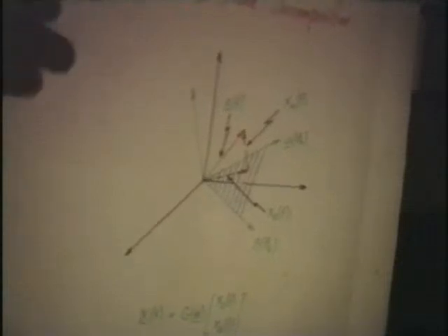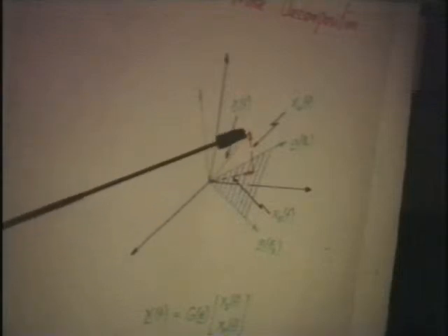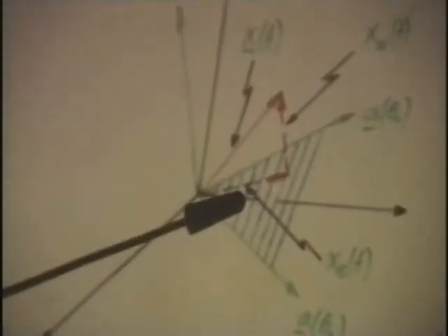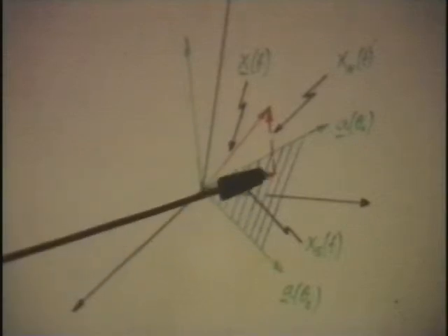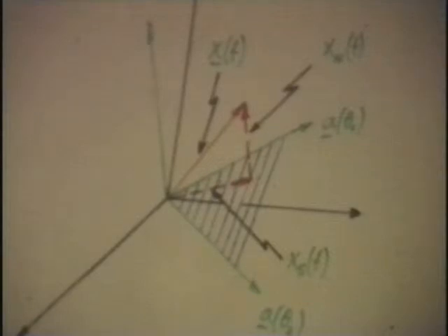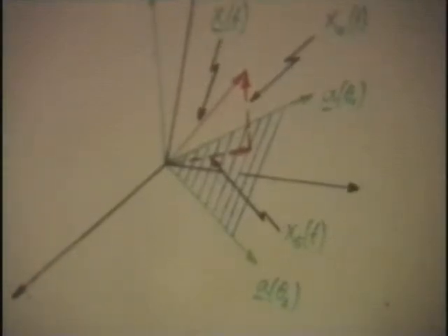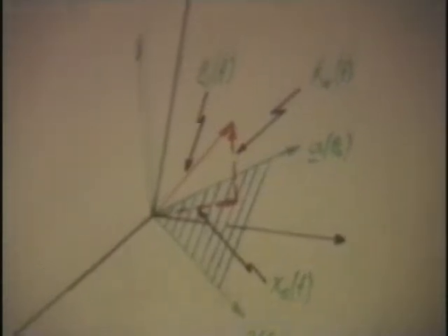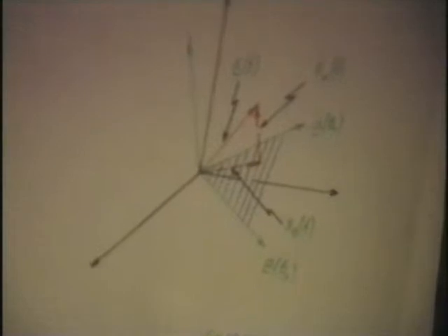The idea is to do the encoding not in terms of xt, but in terms of the projections on the signal and noise subspaces. If you know xn of t, xs of t, and the signal subspace, you can recover xt. So you have two equivalent representations which you can choose according to the simplicity in deriving the estimator.